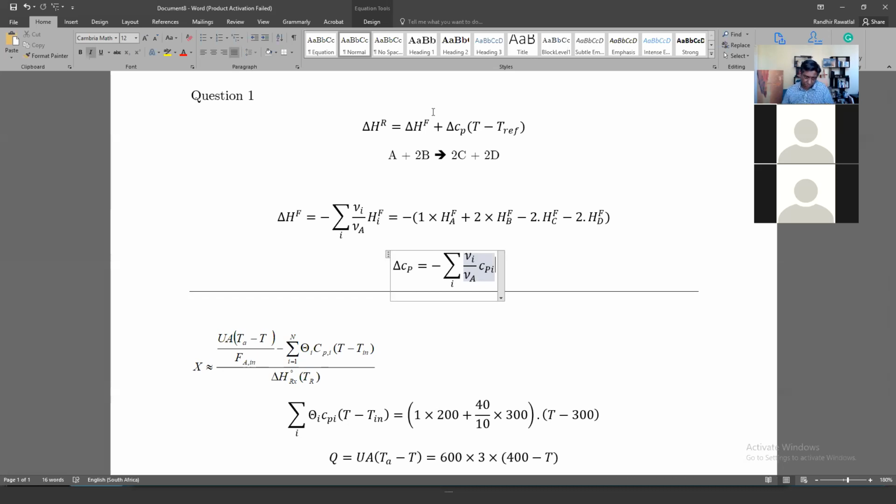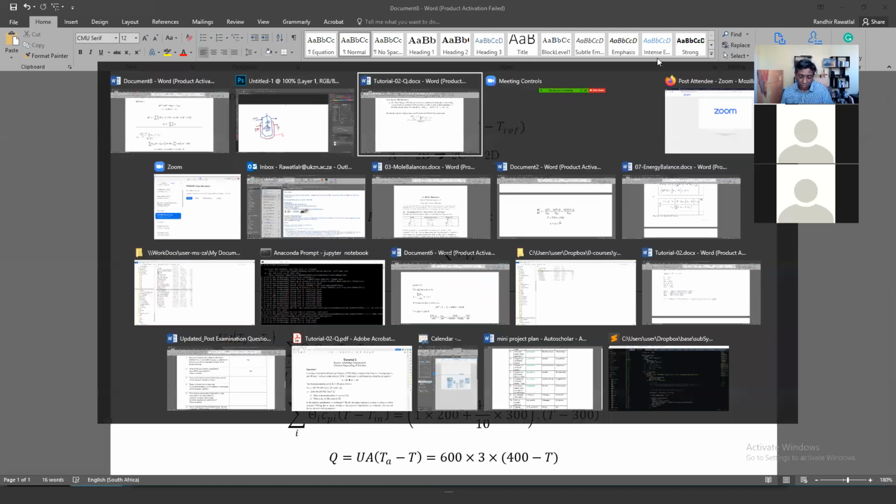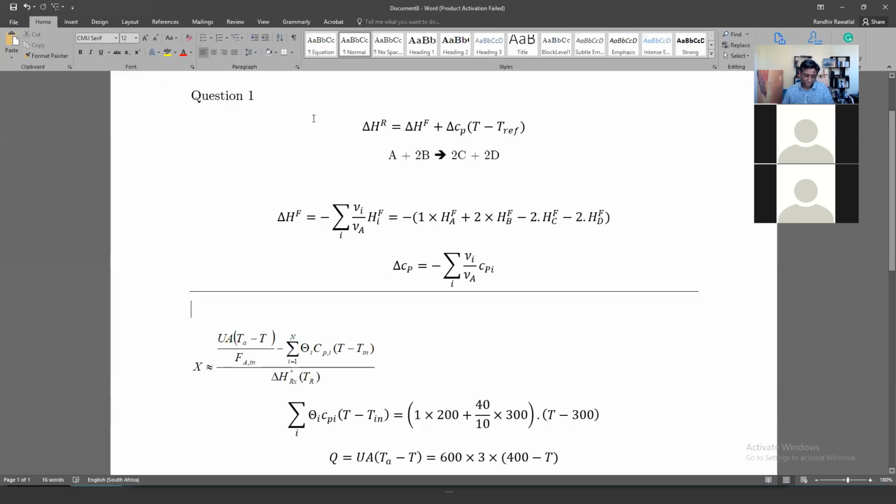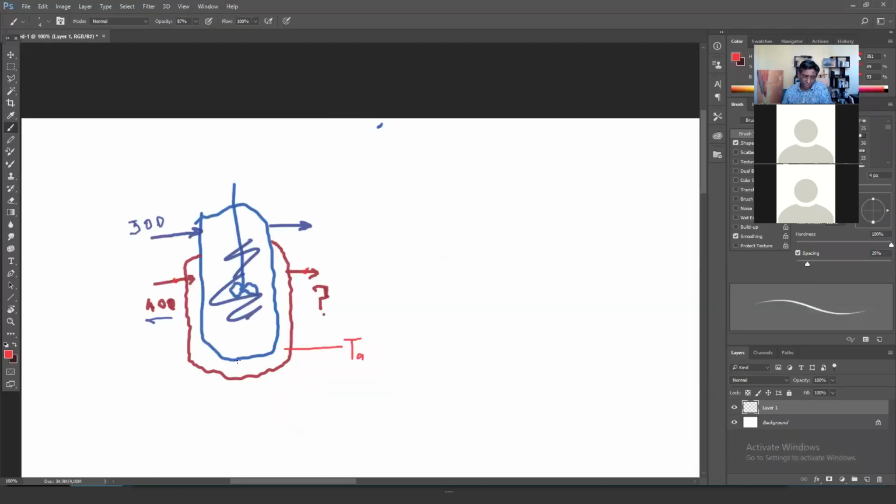So does the 400 Kelvin stream act as a cooling medium? And we actually don't know as yet because I didn't work it out. So when you do the calculation, you'll find out whether it's above or below 400 Kelvin. So whether or not this thing is playing the role of heating or cooling is totally dependent on the temperature that you have here. So if this is at a temperature of 600, then the 400 is actually cooling it.